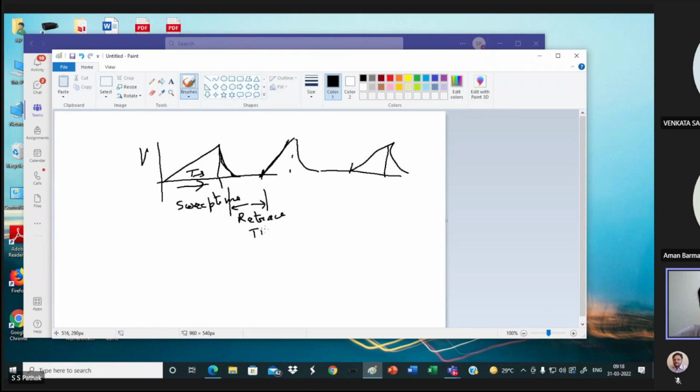So this kind of circuit we need to make. Why? Because if I apply this to a display system on the x-axis, it is increasing with respect to time. So this is low voltage, high voltage, higher, higher. I'm calling this my Vs. So 0 to Vs, it is increasing on the x-axis deflection plate, and that is calibrated with respect to time.